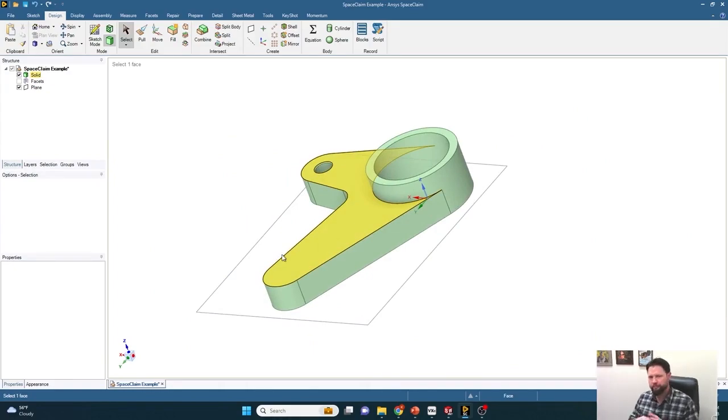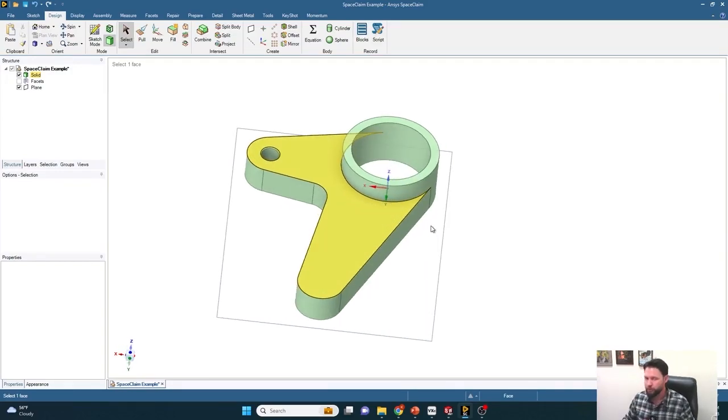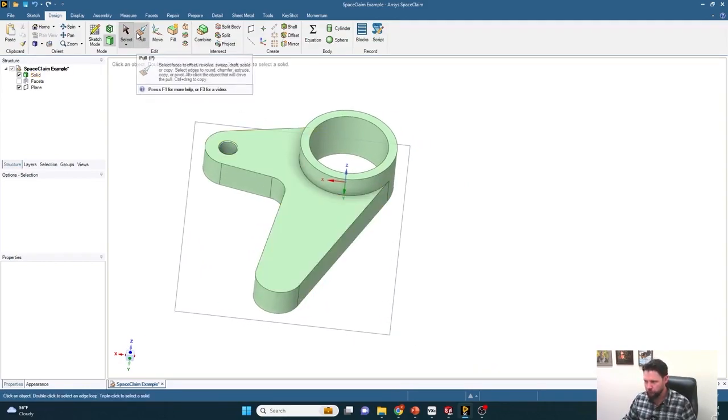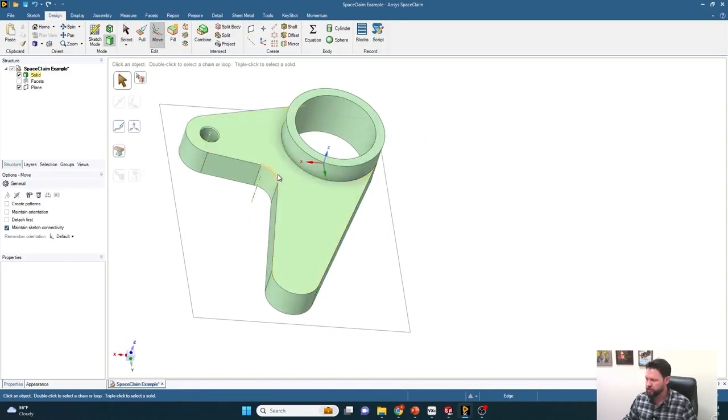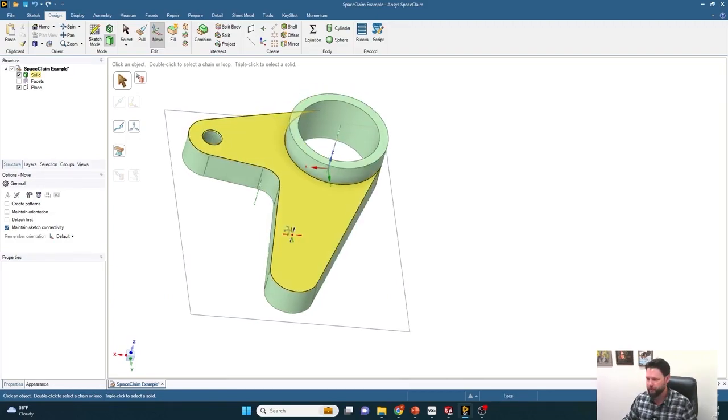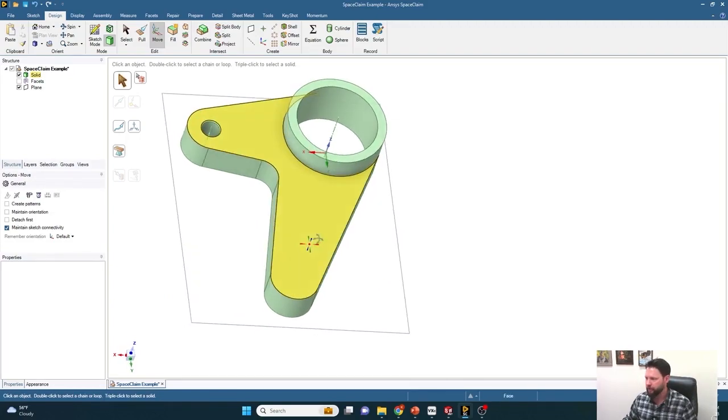So there's some surface wrapping in here, but this really shines for me on creating geometric features. This is very, very fast just because of the way that you create geometry and how you can edit them. What's really cool once you get done is, again, I'm moving off of the pull tool, just something else you can do. Let's say that you want to change the angle of this arm here with respect to the rest of it. Maybe you need a different angle.